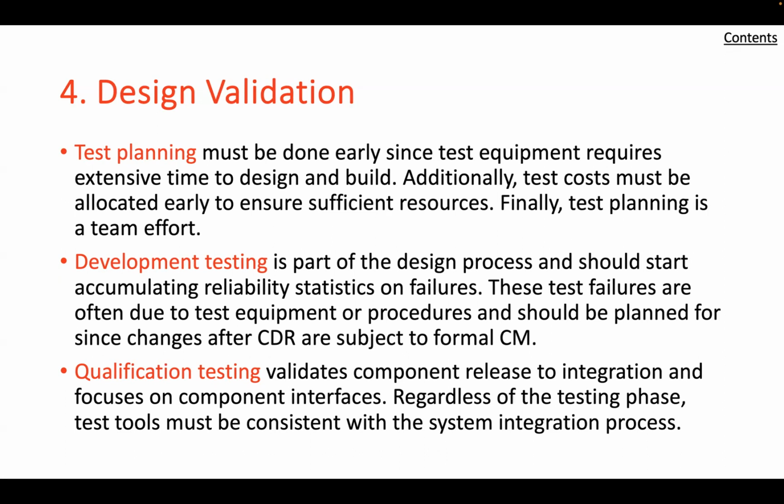Moreover, the assessment of a component's adherence to specified parameters, tolerances, and values usually requires the test equipment precision to be several times better than the allowable variation in component parameters. This requirement sometimes calls for precision greater than that readily available, involving a special effort to develop the necessary capability.